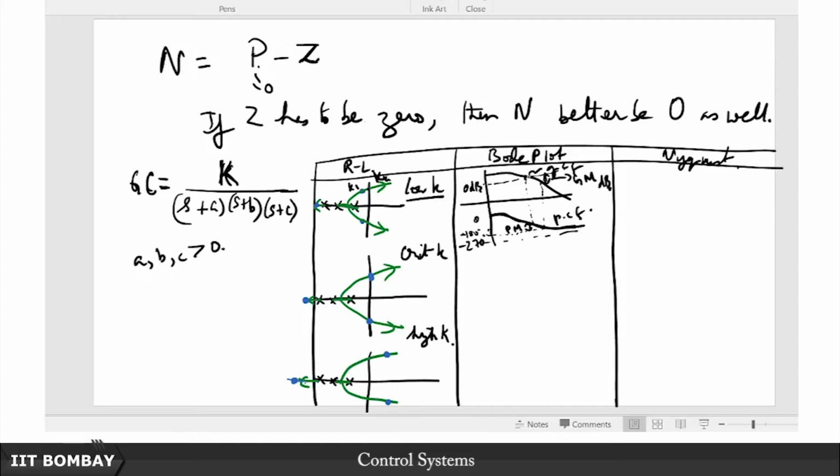So you first have the gain crossover frequency, then you have the phase crossover frequency, yeah, that is typical of a stable open loop system which is also expected to be stable in closed loop, okay. That is why you often see people say that gain crossover frequency being less than phase crossover frequency is a good thing. The implicit assumption, as I also said when discussing Bode plots, is that the open loop system is stable. All our discussions are now predicated on the assumption that the open loop system is stable. Alright, what about this situation here?